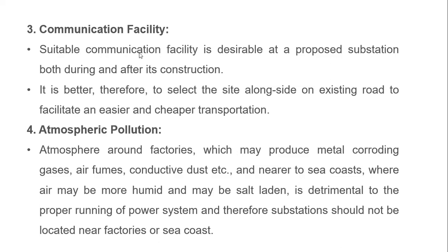These are the various points that will be considered for deciding the rating of the substations. Why? Because the rating will change: day by day the population increases, and due to that we reach higher load densities. For that increased population, we require additional rating of those substations, depending on either the service area of that substation or installing new substations.